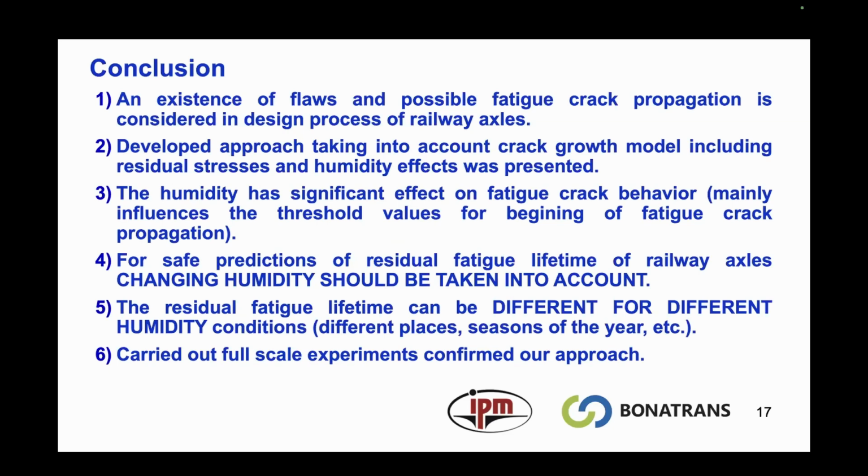And if we are talking, for example, about applications in polar areas and so on, it is good to know that there is an important shift down of the threshold values, and it is necessary to consider this lower threshold for fatigue crack propagation.